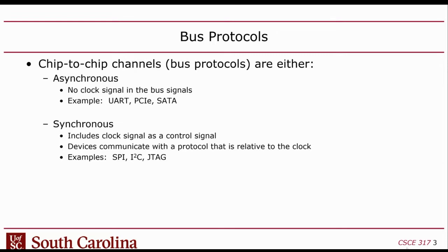Now, it's not quite that easy. In practice, I've found that it's kind of a pain, because in order for that to work, you not only have to encode the data in the channel, but you also have to put clock synchronization characters at regular intervals. Otherwise, you lose sync. So you have to put special control messages in there as well. It's kind of a pain, although the interfaces will take care of that, depending on what level of abstraction you're working at.